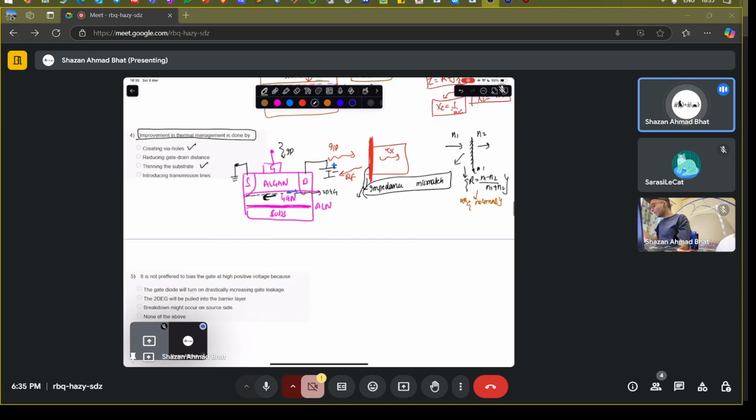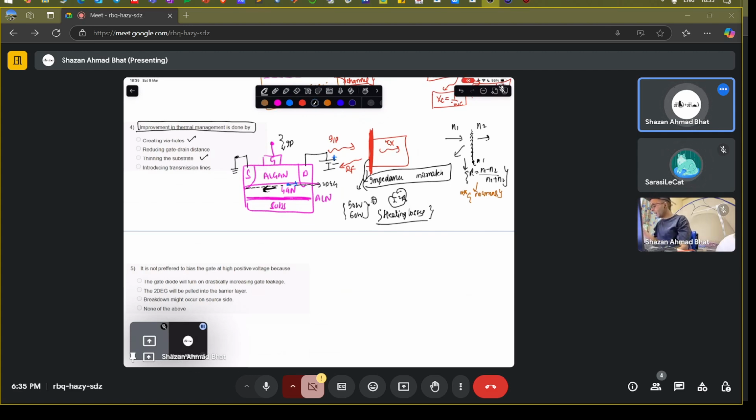Now you are dealing with huge power, of the order of 50 watts, maybe 60 watts. So this is a lot of power. And there are I square R losses, which are basically the heating losses in the device. And where is that heat going to go? That is obviously going to remain in the gallium nitride.